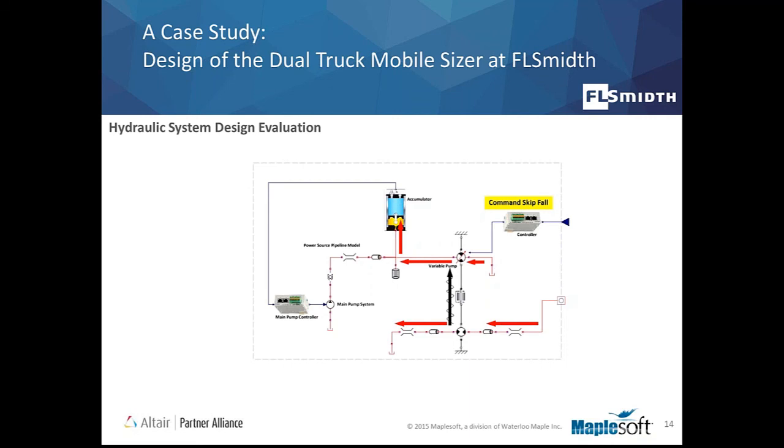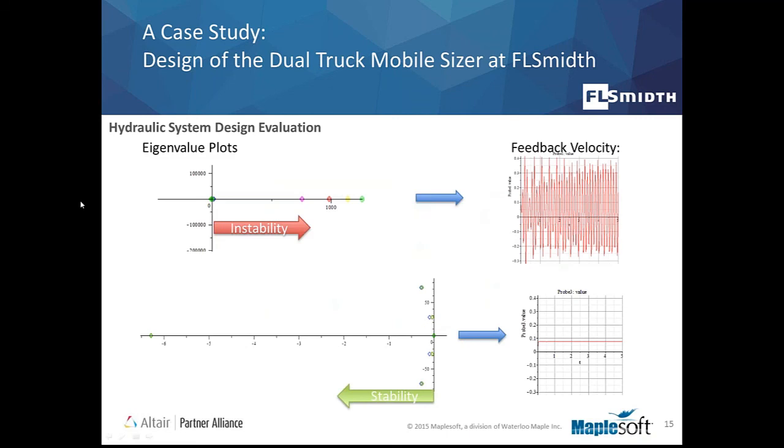One of the concerns that got evaluated by our analysis, by being able to go from a MapleSim model to a rigorous mathematical approach, was the issue of vibration. We were able to use Maple, with its mathematical and symbolic capability, to linearize the model, look at the eigenvalues, and look at the possibility of vibration.